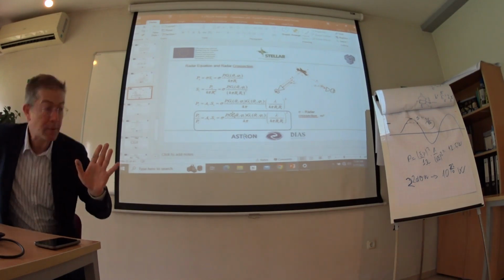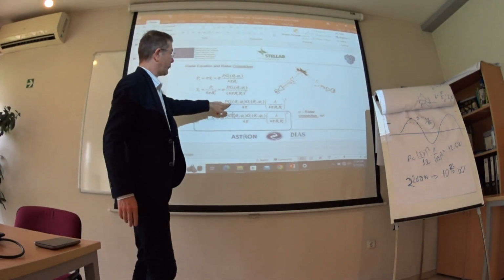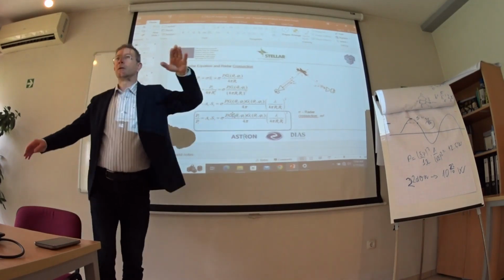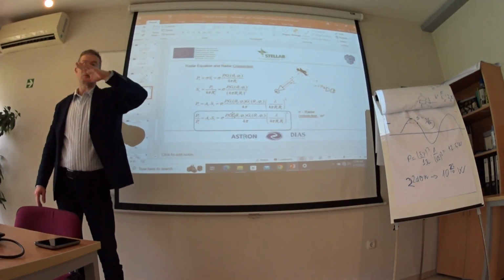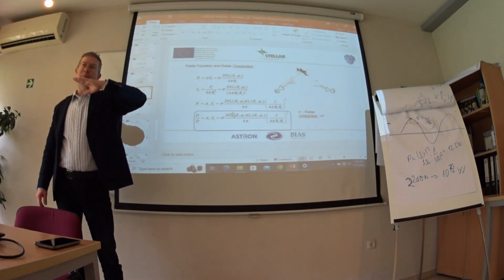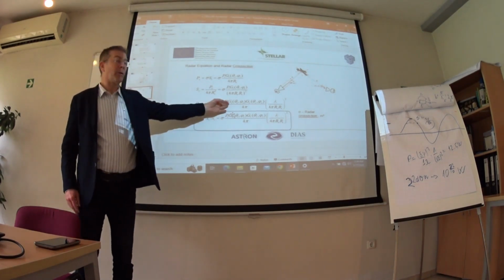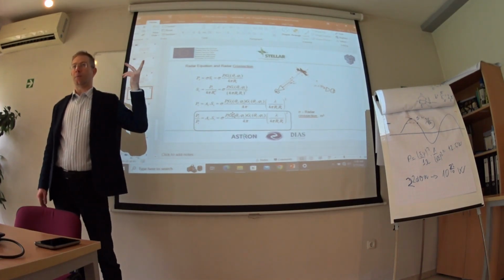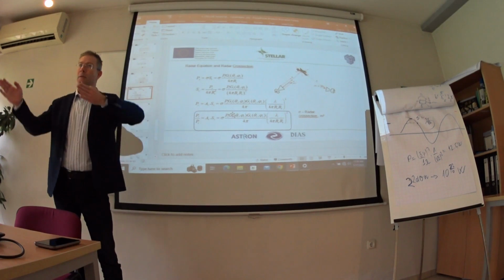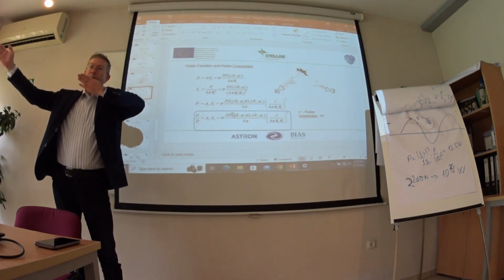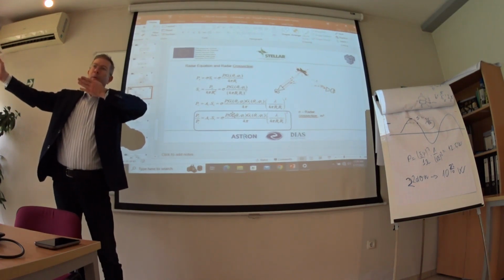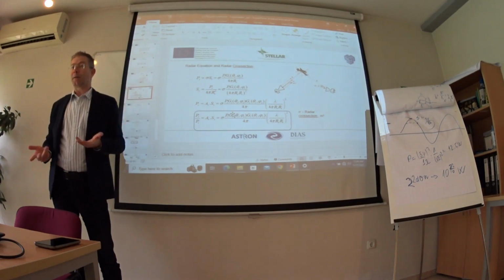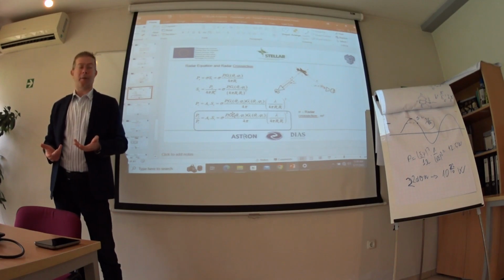In ideal case, this will be the peak gain of the transmit antenna, peak gain of the receive antenna. But in real time, it's not so easy to pick the target. So let's say instead of 20 decibels of gain, we will get 15 decibels of gain. This is the important one. In an ideal case, the antenna will point at the target, and we use the maximum gain of the antenna. But this rarely happens.